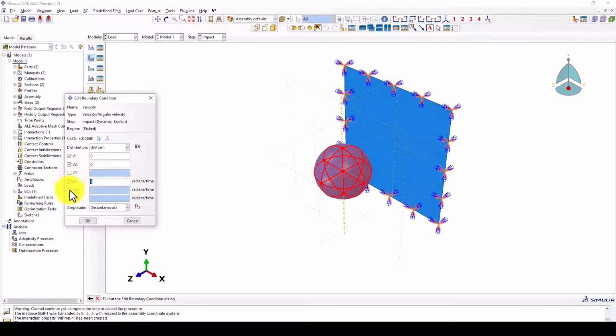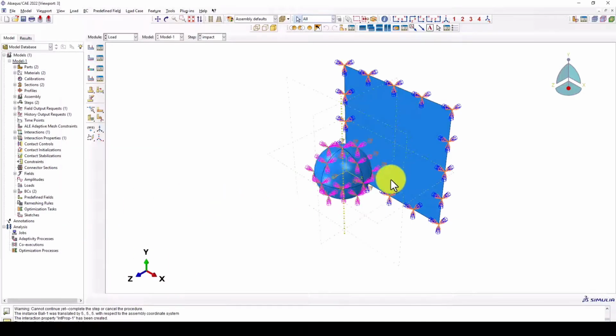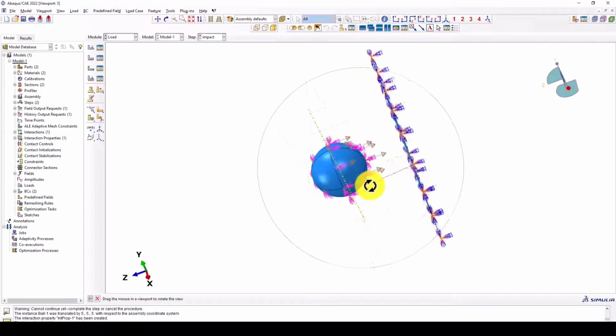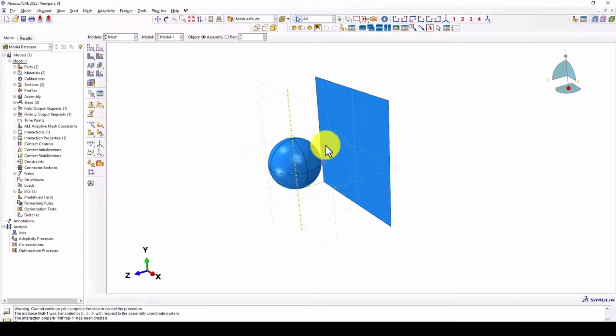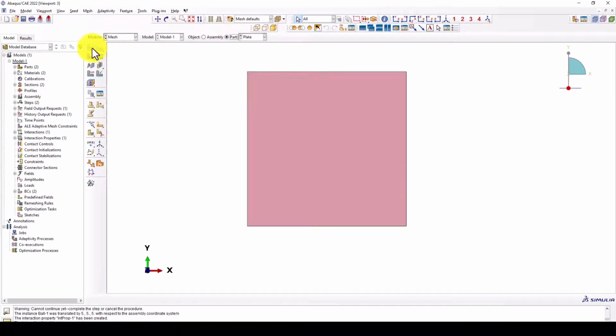So I'll include Young's modulus, shear modulus, bulk modulus and Poisson's ratio. Young's modulus is also known as elastic modulus. Bulk modulus is the volumetric stress upon volumetric strain, and we know about the Poisson's ratio. The negative sign in the Poisson's ratio is used to show that the deformation is in the opposite direction to the longitudinal.